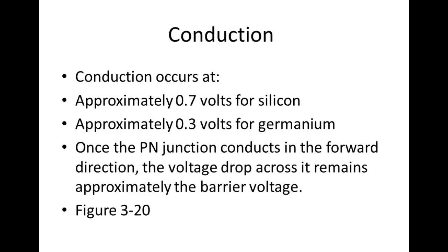If we look at the forward bias curve on a diode, it starts off conducting a little bit because there's a path. Then right around 0.5 for silicon, it would start kneeing. Then it shoots up, but at an angle. This would be IF, the forward current, and this would be VF. So that VF increases just a little bit over the range of operation because it is not a conductor. You understand? Even when it's forward biased, it has some resistance.